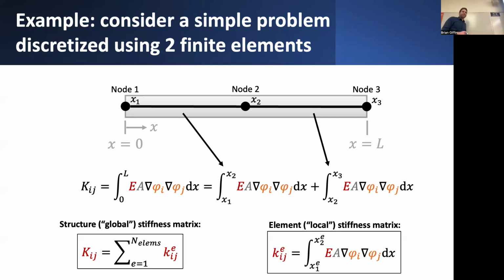But there are certainly other options that we could choose, such as perhaps defining elements that consist of not just two nodes defined at the ends of this particular element, but maybe you could think of an element that consists of four nodes, and this particular element might have some interpolated representation of the displacement field local to that element that is expressible in terms of a similar kind of setup here, where the individual nodal displacements are really nothing more than these four discrete nodal values, but we would want to come up with some smooth interpolating function that passes through all of these four different points.